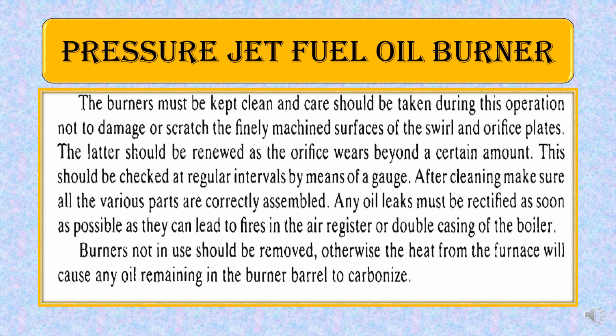Any oil leakage must be rectified as soon as possible, otherwise it will leak into the furnace and cause a fire inside it. The air register or double casing of the boiler is also included in the fire part of it. A burner not in use should be removed. Otherwise, the heat from the furnace will cause any oil remaining in the burner barrel to be carbonized.